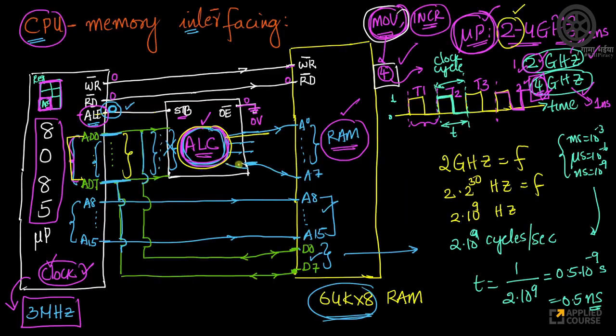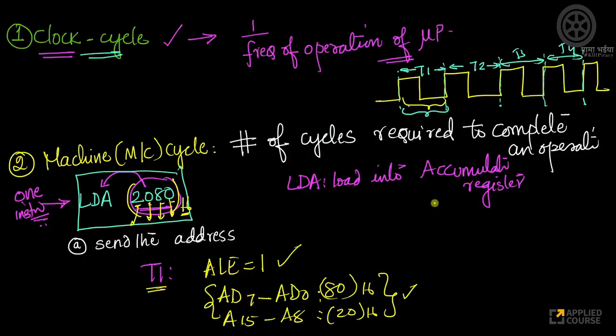The same values will be here. So as far as the RAM is concerned, it is seeing all of these 16-bit addresses, even though the CPU is not sending addresses anymore, because whatever address it was sending earlier, we copied into the address latch chip, and we are now making the same values visible here because my OE is set to 0. Very simple concept till now.